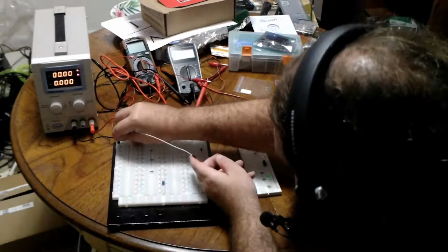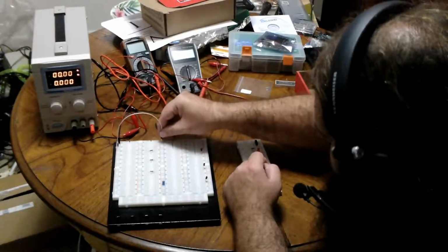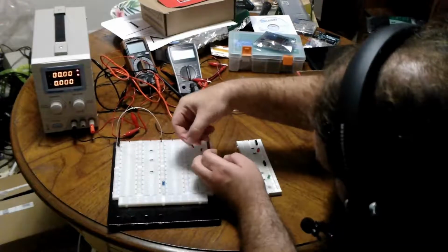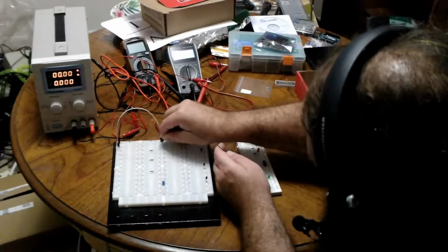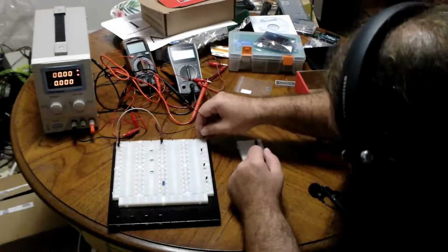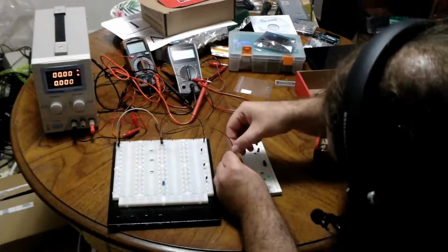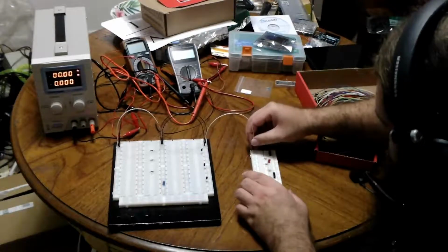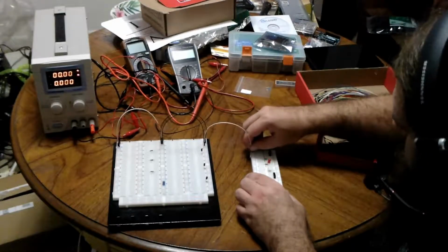So to make life easier, I'm going to put some jumpers across this breadboard, just so I can get the power through any of these rails. And then we'll connect over here to more positive, to negative here, to positive there, negative there, negative there. And then finally, I'll jumper that power across to this secondary breadboard. Now, why am I using a second breadboard?